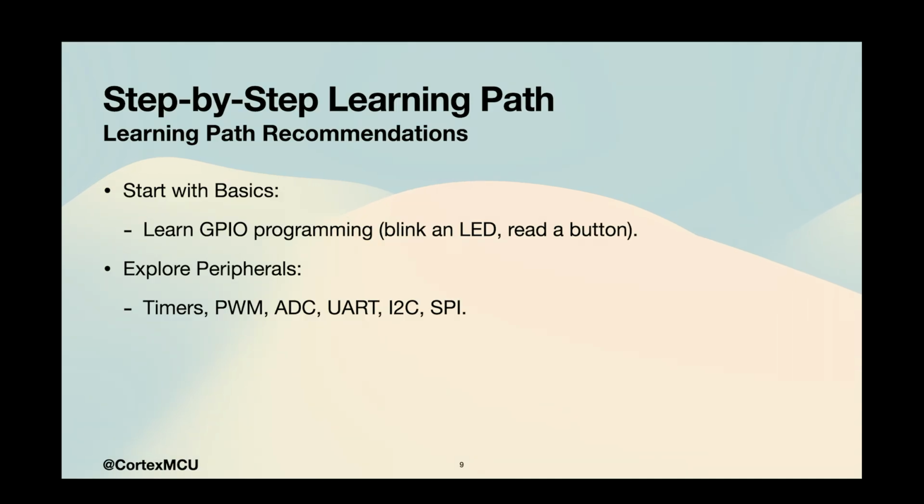For the learning path, step by step, I recommend that you start with the basics, for example, learning GPIO programming. A simple project is also called lighting the LED. The second step is to explore peripherals.